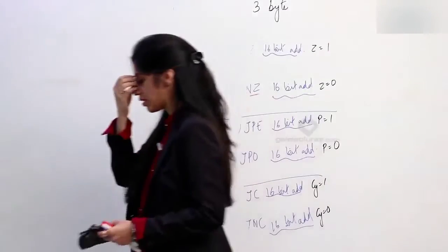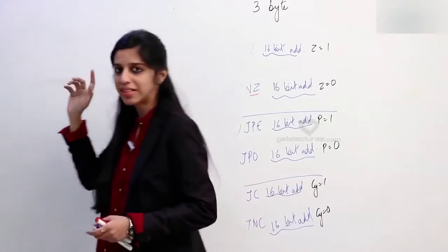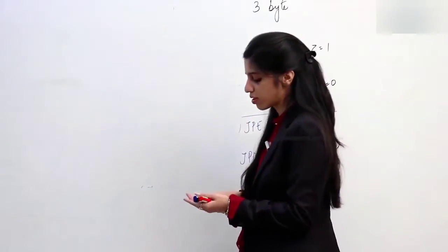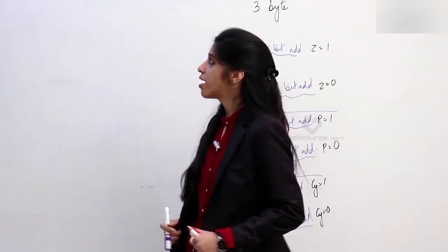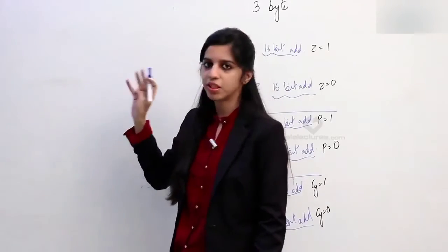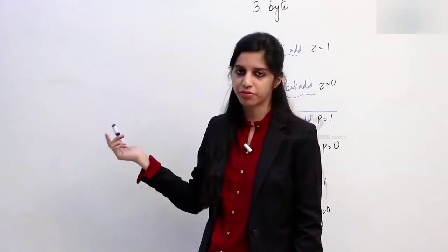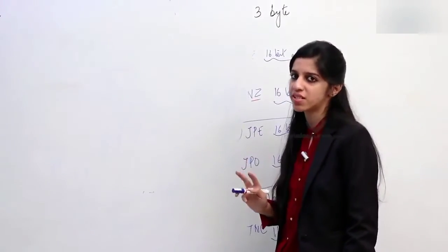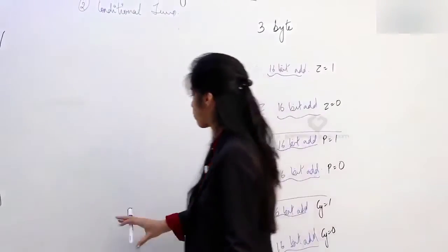So already we have seen that unconditional jump had 10 T states, it had 3 machine cycles. Conditional jump is not the same. Why is it not the same? Because here we need to check the condition, we need to check the flags if the jump has to be made or not, and checking the condition requires 2 T states. It is a 2 T states long process.